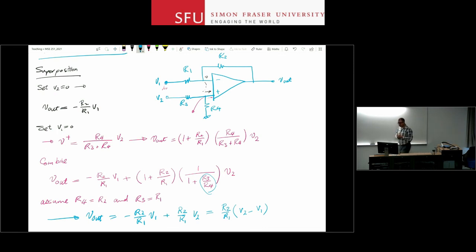You may or may not know them. In most cases, you want to have some safeguard at your end of the business, in your circuit, to make sure that those variations in properties of V1 and V2 do not affect what you intend to do with your circuit. You basically want to subtract V1, V2 from each other and multiply the difference by the gain.